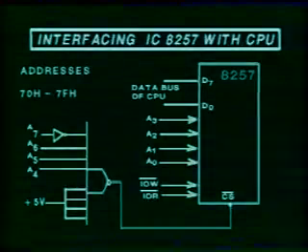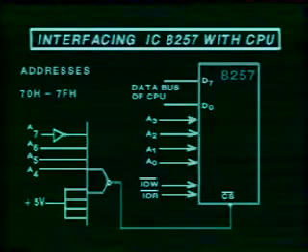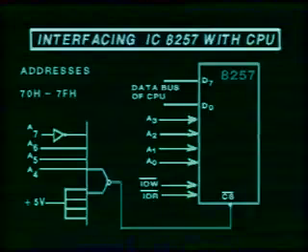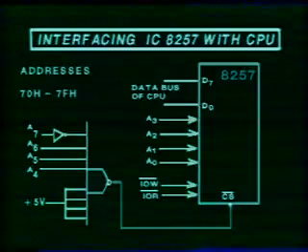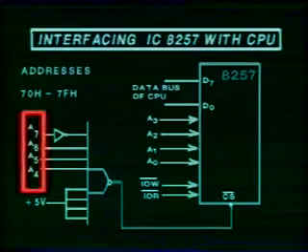Having seen this diagram, you will now see the interfacing arrangement for the various lines in the DMA controller when the DMA controller is working in a slave mode. In this diagram, we have assumed an I/O map such that the DMA controller has got its registers addressed from 70 to 7F. Therefore, the DMA controller is selected with the hexadecimal digit 7 corresponding to the address lines on A4, A5, A6 and A7.